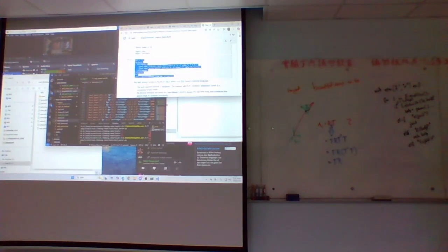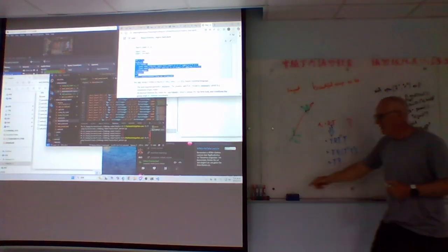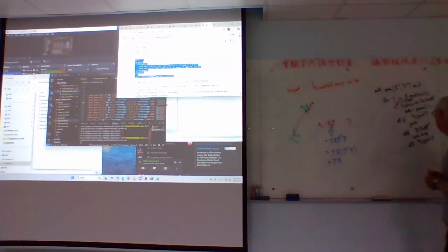Also, for the motion, I don't think you want your robot to move here and then latch on there, because there's quite a bit of noise usually in the position of your vision system that you detect the holes at, and there's noise in the motions in your servo control and everything, right? So what I would do is, you know the direction of the hole.